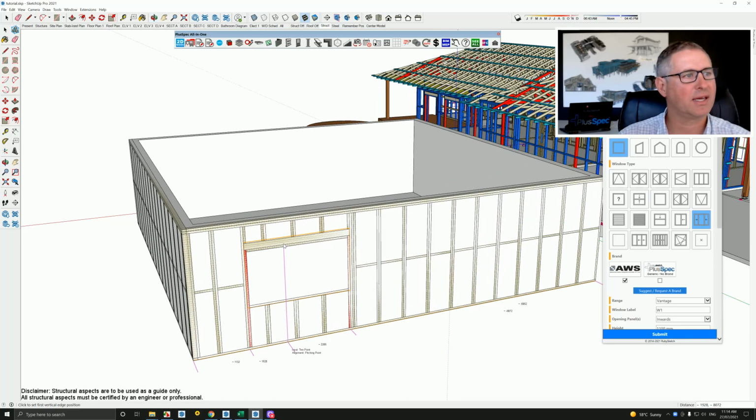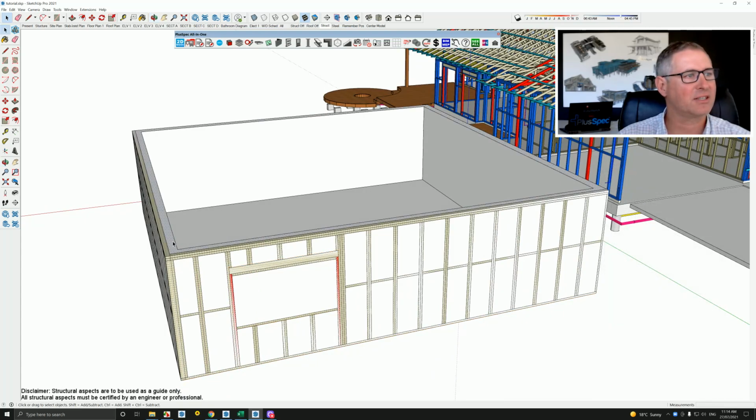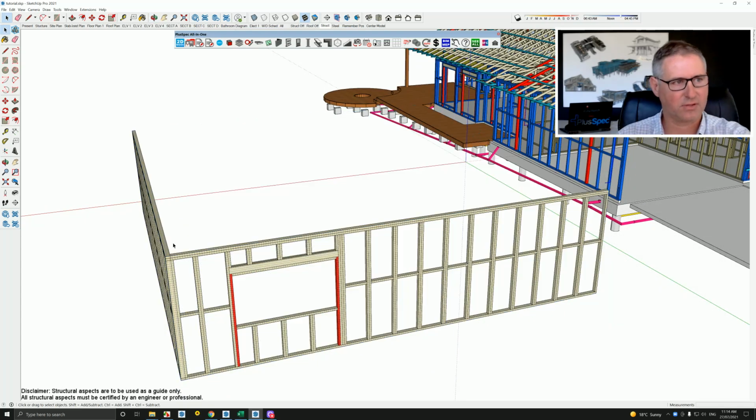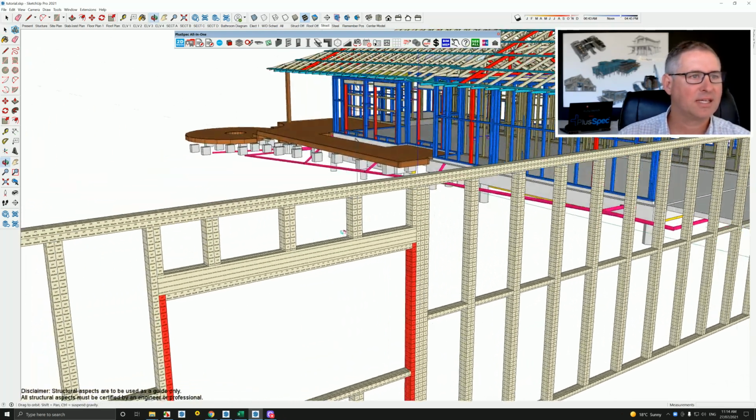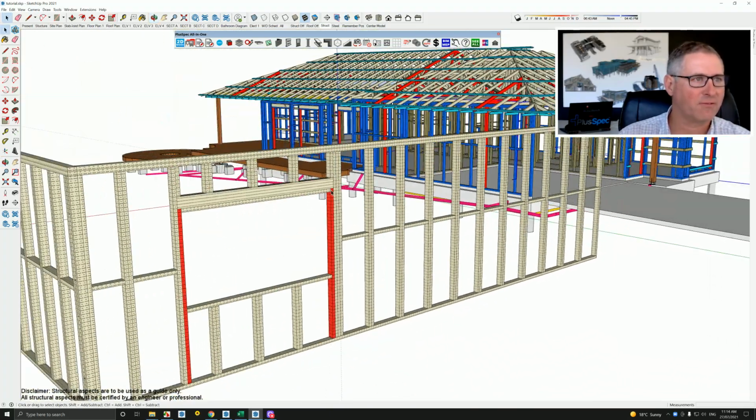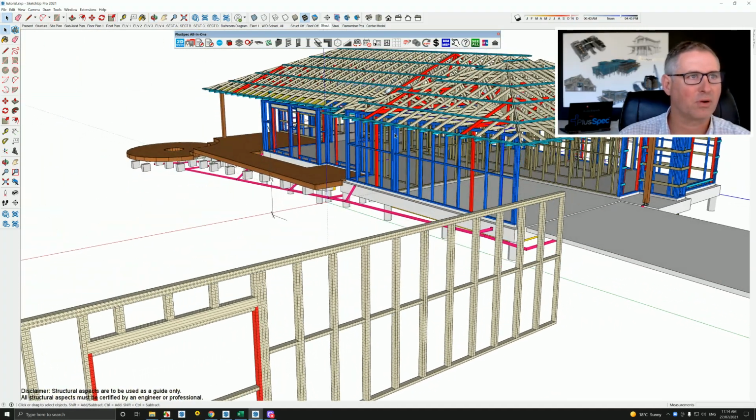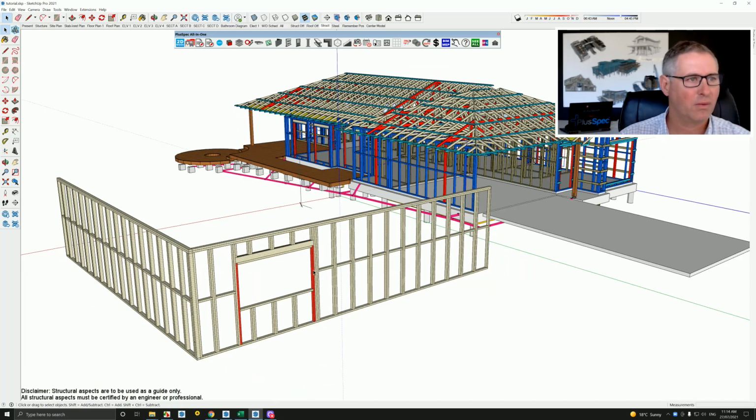You can see there that it's actually cut the structure, and that SketchUp model is just over top of it. I'll delete that. And you can see that now it's actually started to signify where load is. So in the other model we spoke about load path before, we can see that there would be load there because this is holding more weight.